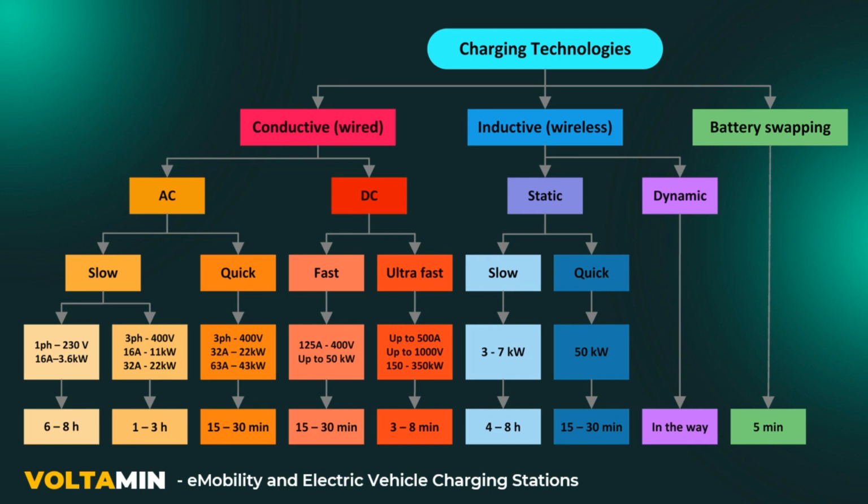Although in the first years of e-mobility development the trend was to improve AC charging power up to 43 kilowatts in some models, the present approach is to limit AC charging to less than 22 kilowatts or often 7 kilowatt single-phase and 11 kilowatt three-phase. Fast charging is performed by the DC chargers, which are becoming standard equipment for all EVs.